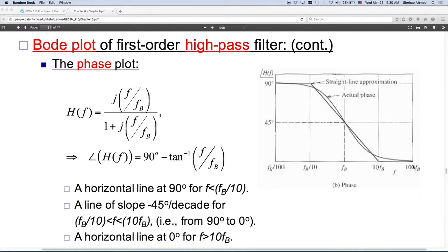Right? These are all RC circuits. So the capacitor will either be phase shifting, dominant and acting on the AC signals, or the resistor will be dominant and the capacitor will be an open circuit. And that's why we always see a phase shift of either 0 or 90 at the asymptotes, for the low pass and high pass filter. For the high pass filter, it's 0 where? At high frequency. Right? Forget about all the math.